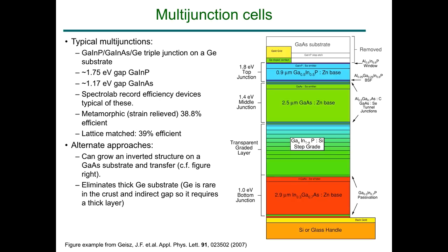And as I had mentioned, interfaces are really common places for recombination and efficiency losses. So you have to be really precise with how you make these and stack all these different materials on top of one another. So a lot of multi-junctions are used in concentrator applications where you just get as much light on it as possible to push efficiency as high as possible.